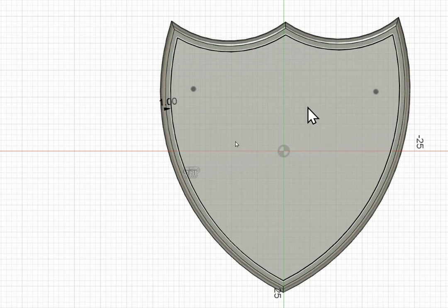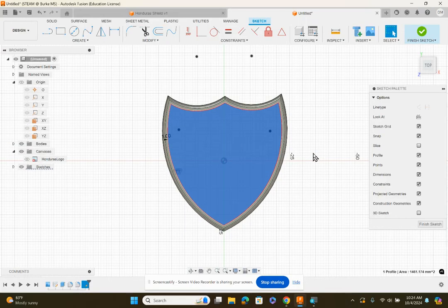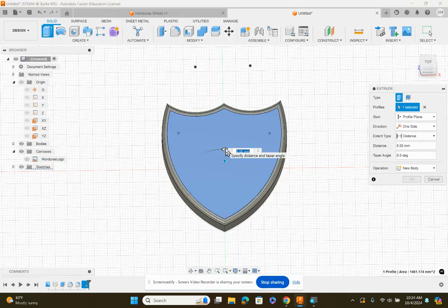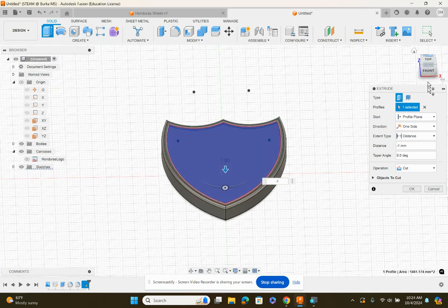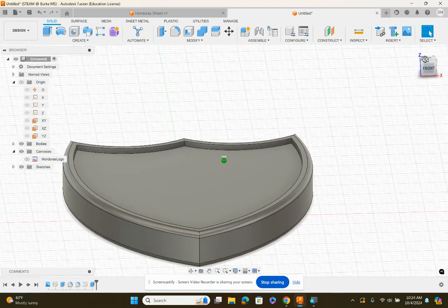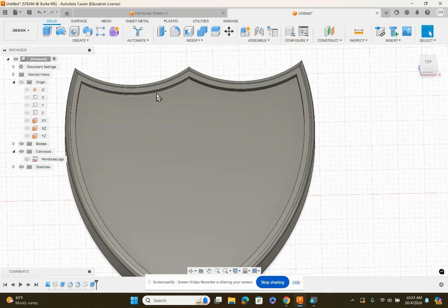So what I'm going to do with this one is I am going to lower it so it sinks. And so I can do a couple of things. I can do push-pull. I could do extrude. Let's do extrude since we're used to that. And then I'm going to go negative. And when I go negative, notice that this is going to say cut. So because we're going into the body, it says cut now. And I don't know if 1 is okay. So let me just click OK and look at it. Remember, it's 7 high and now it's 1 down. I think that's fine. That's fine.